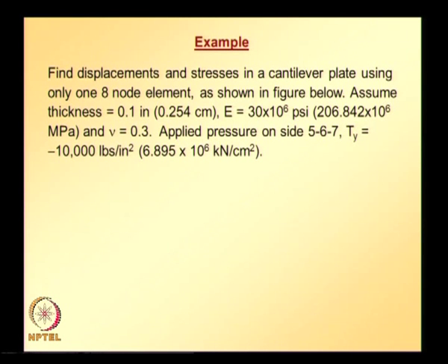The difference from the earlier examples with the 3 node triangular element and the 4 node quadrilateral element is that there we had concentrated forces, where it was not required to evaluate the equivalent nodal load vector by integration.